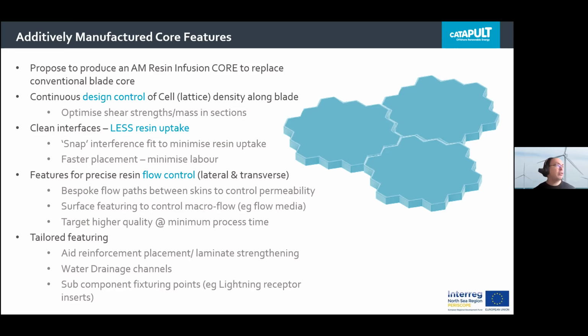So you could imagine on the top surface or both surfaces, you could have a dimpled surface maybe or a spiked surface that would penetrate the dry fiber laminate stacks to effectively help pin them, locate them, but also potentially aid transverse strength of the laminate, as well as actually providing an opportunity for internal resin flow media to be designed within that body.